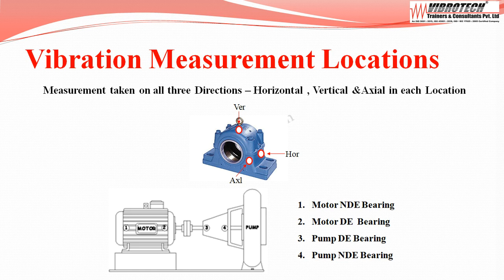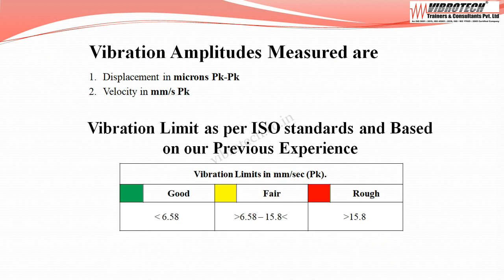Measurement locations are motor non-drive end bearing, motor drive end bearing, pump drive end bearing, pump non-drive end bearing. Vibration data are collected in terms of displacement in microns peak to peak and velocity in millimeters per second peak. Now onto the vibration limits.